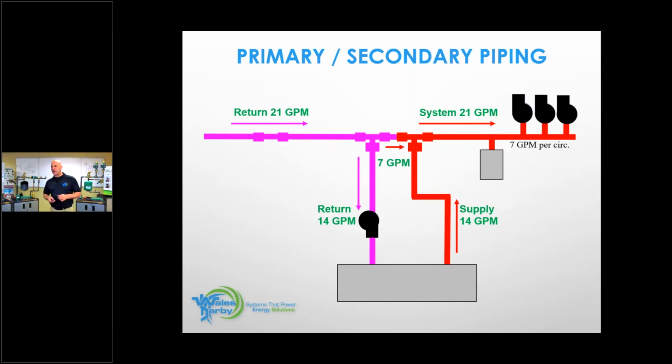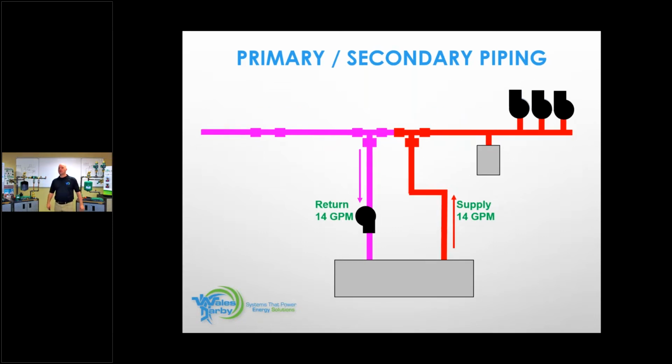It will be in the bypass mode, and guys will respond. So keep it going, keep typing. So in this scenario, we're going to bypass water across those closely spaced T's because our system flow is greater than our boiler needs or can handle, for that matter. So this is a scenario where realistically we're over pumping. And this will get into the zone valve circulator conversation we'll have in a little while. And again, there's no right or wrong. We're just going to throw a couple things out there.